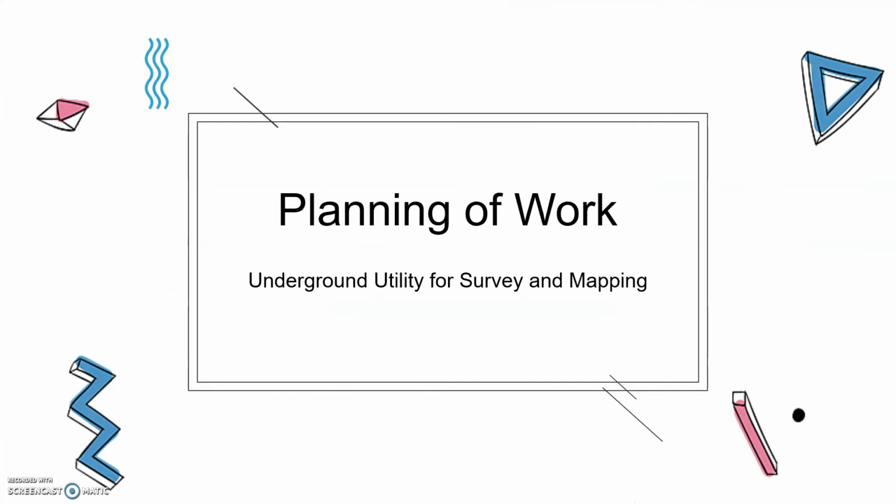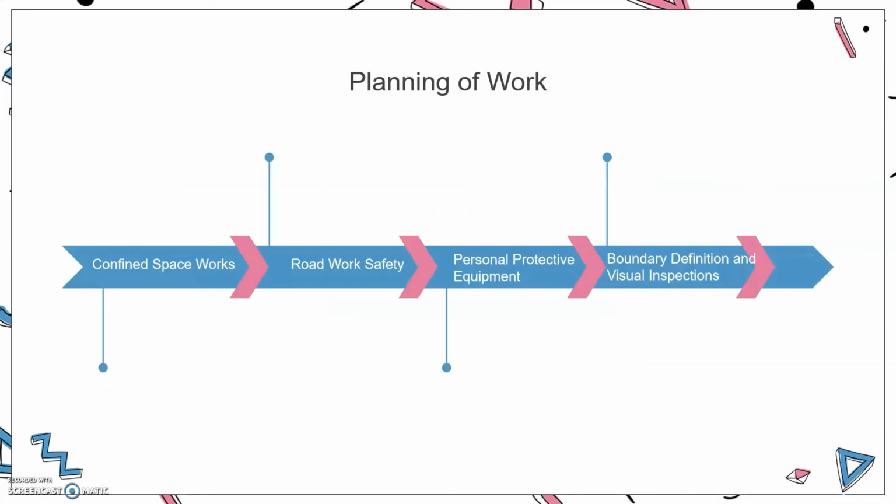Planning of work. Staff entering manholes will have been trained and awarded the certificate for confined space works. Due to the nature of the works, manhole entry is not recommended for utility surveys, as information can be acquired by sonde, and in case of being unable to survey due to slip or flow or any other dangerous possibilities, photographs will be taken for record purposes.